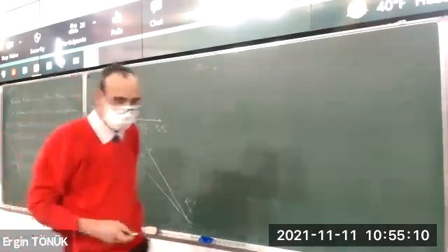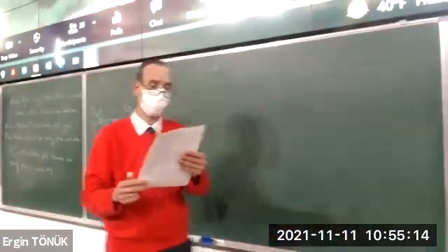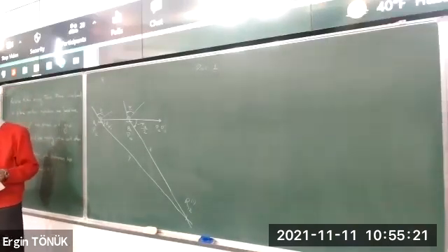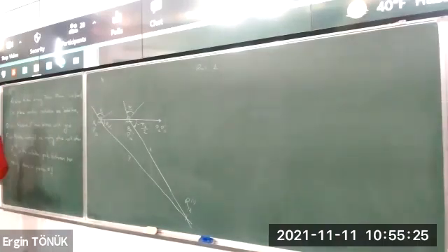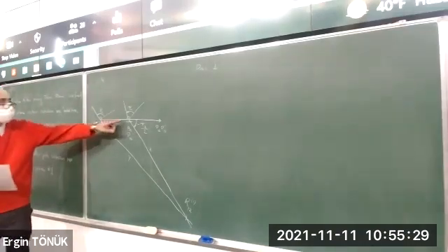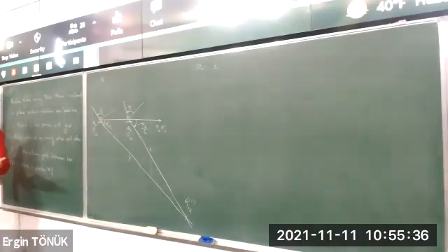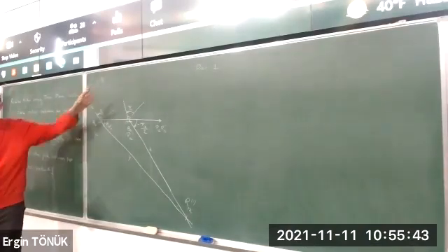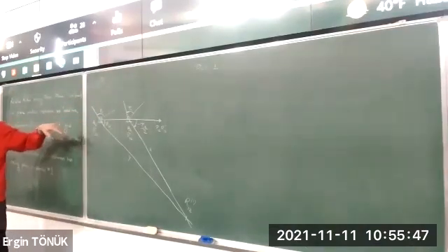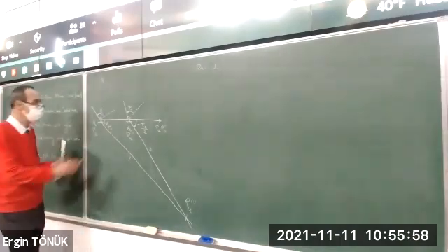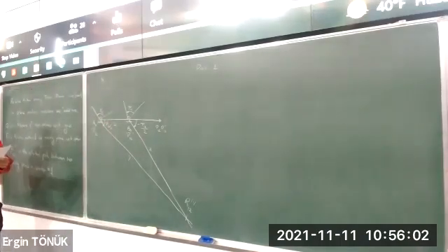Actually, I'm going to apply it on this figure. So, well, you all know that what is important for the motion is not actually the link length, but link length ratio. So, you can take this distance 1 unit. Whatever 1 unit is, it can be 10 centimeters, it can be 5 inches, whatever, okay? So actually you normalize A2, A3, A4 with respect to A1, okay? So you can have a small 4-bar or a big 4-bar, but as long as the ratios are the same, it will do the same motion. So assume this is arbitrarily 1, whatever 1 is.